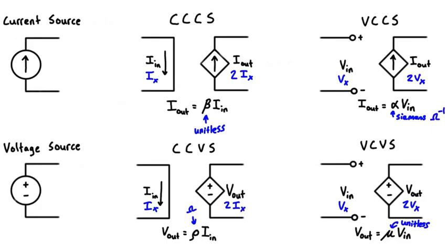So when you're solving these problems, what you have to do is figure out what the controlling voltage or current is for the type of dependent source that you have. And usually you're given the multiplying factor. So once you find the controlling voltage or current, you just multiply the multiplying factor to it, and then you'll have your dependent voltage or current as that power source, and then you'll be able to proceed with the problem as usual, just as if it was a basic independent current or voltage source. So yeah, I think that's it for now, just some vocabulary.